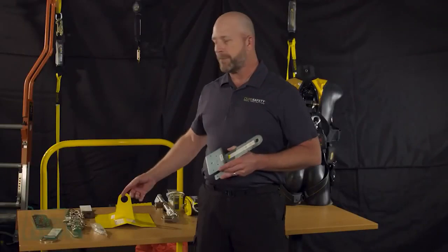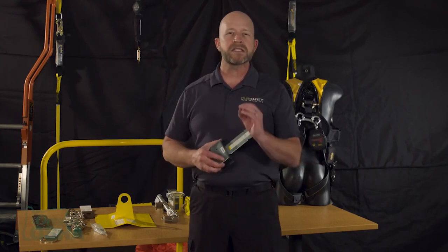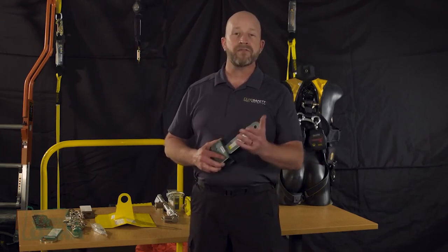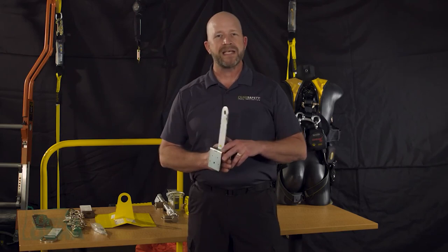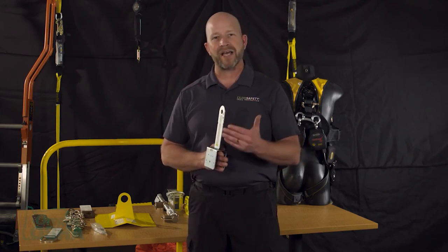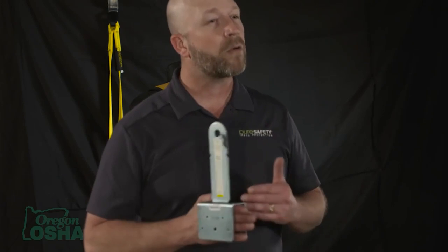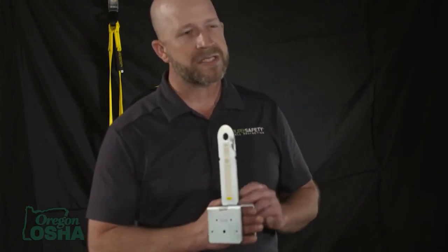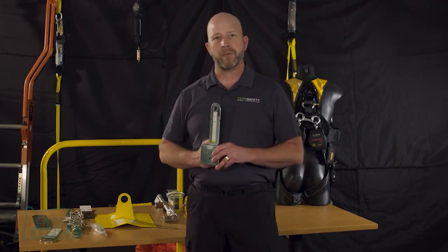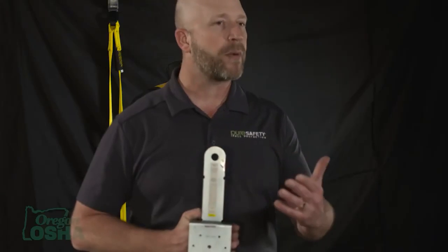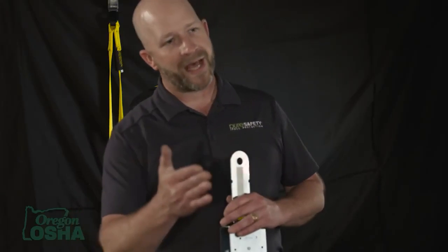With any anchorage attachment, beam strap, or other device, it is still imperative that when we're on site, other than following the manufacturer's instructions, we still verify that the structure we affix this to isn't just something random, that it is still evaluated either by a competent person or by a qualified person. Laying one truss doesn't make it structurally sound, and at some points, no doubt, you will have to have somebody actually do engineering or prove that it is capable of withstanding the forces. We talked about working on top of a top plate and that the framing is up, but is it really an anchor?